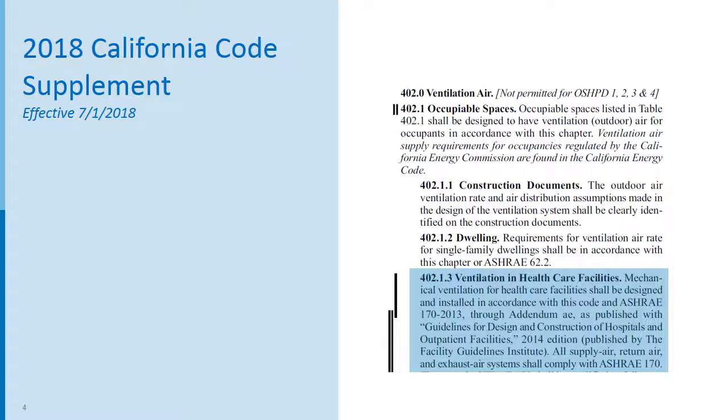It goes into effect next week, and that includes a line that says follow this code and ASHRAE 170 for healthcare facilities, which seems to say that, hey, listen, for any healthcare building, including the smallest outpatient clinic, you need to use full-blown hospital air conditioning, air changes and pressures and two-pass filtration, the whole deal.